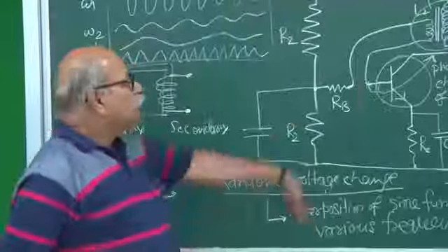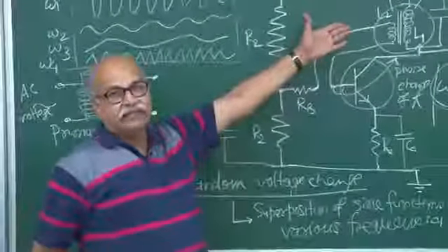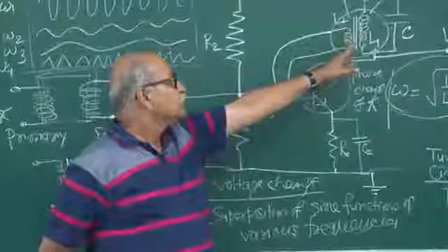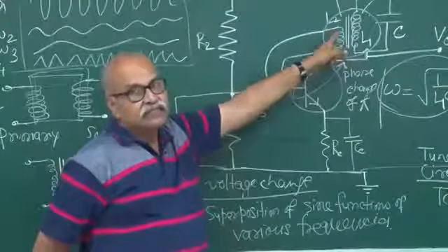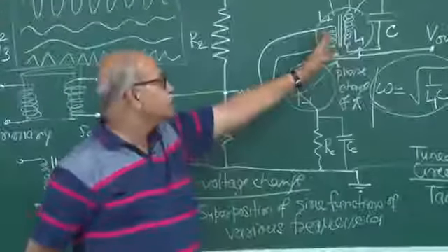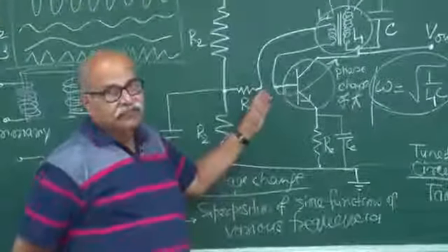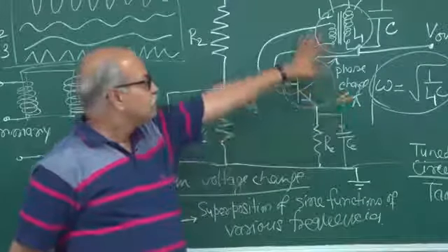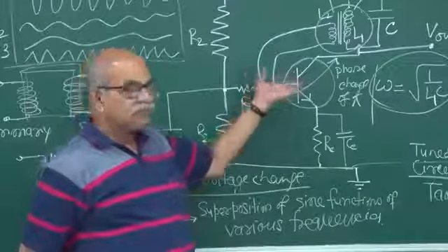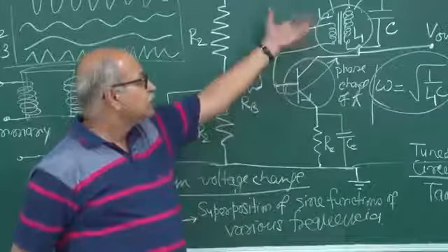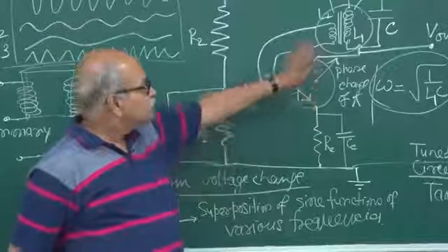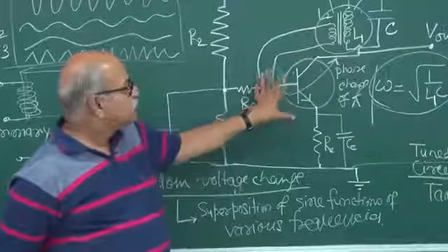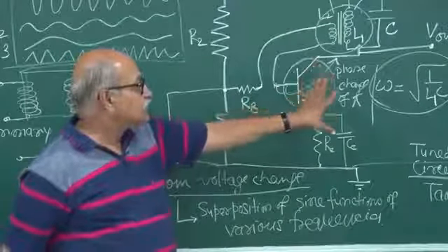And then you get your output with that kind of voltage. How much feedback is taken can be adjusted from this L2. The number of turns here will determine what fraction of this is taken as the feedback. Essentially we need a constant amplitude at the end of it. If this feedback is more than that, we are in trouble. If it is less than that, we are also in trouble. So the number of turns has to be chosen judiciously so that a particular amplitude is maintained.